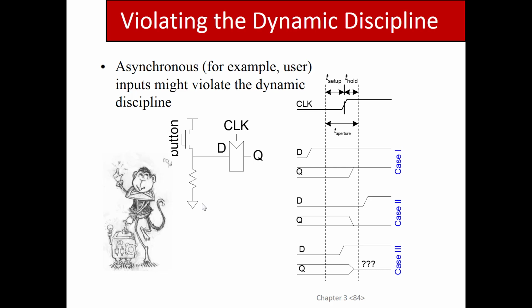If you have a circuit with a button, you have a user hit a button. Generally speaking, you're going to capture that button press with a register, with a flip-flop. You're going to have the button connected as the D input on a flip-flop. So the user hits a button, and you're going to capture that every clock edge, right? We do that in 613.